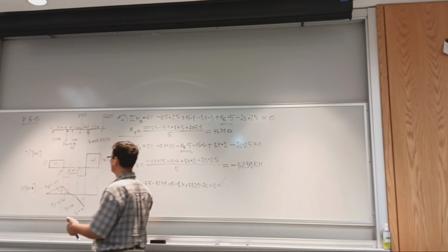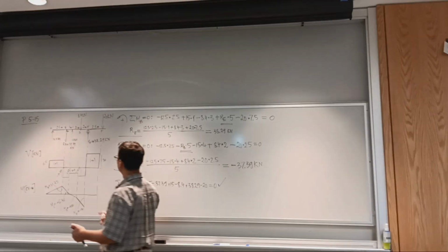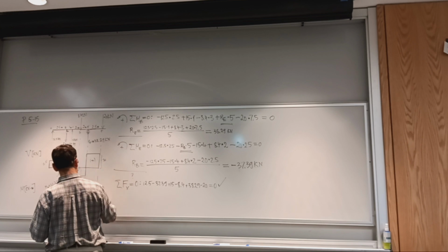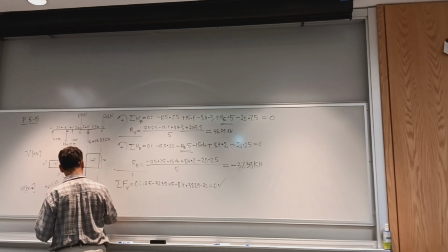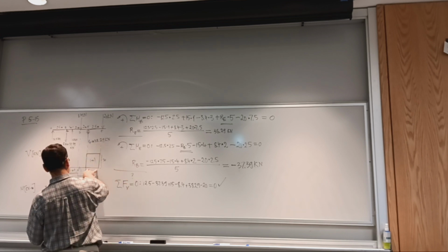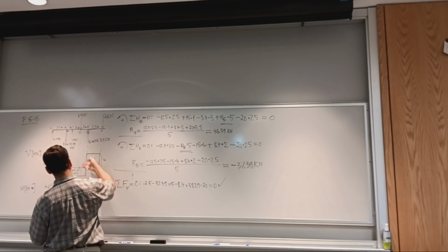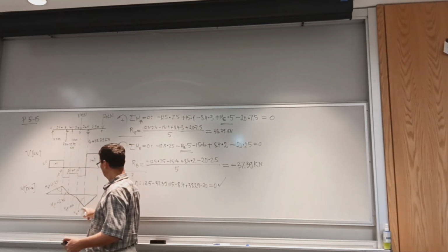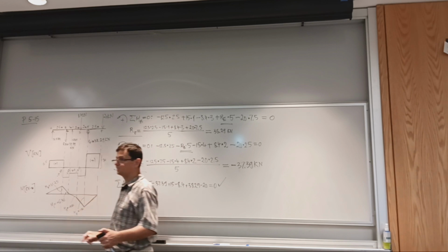All right, so I have here negative 50, the moment at E is negative 50, and it happens to be the maximum bending moment on this beam because with a positive slope of 20, it closes to 0. And indeed, if you take 20 times 2.5, it gets you 50 positive, but I flip it because I went from right to left. Okay, so was it clear?